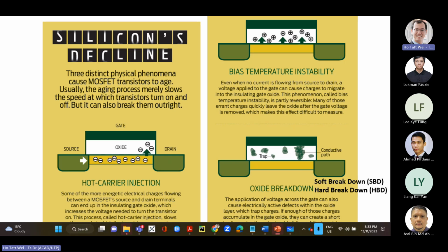It has failed. Okay, so in the case of aging, when you have the charge trapped in the oxides, the transistor is still functioning. The gate is still functioning. It's only that the effective threshold voltage seems to have gone up, because the gate voltage is less powerful to create the conducting channel. So your current is reduced, so things slow down.